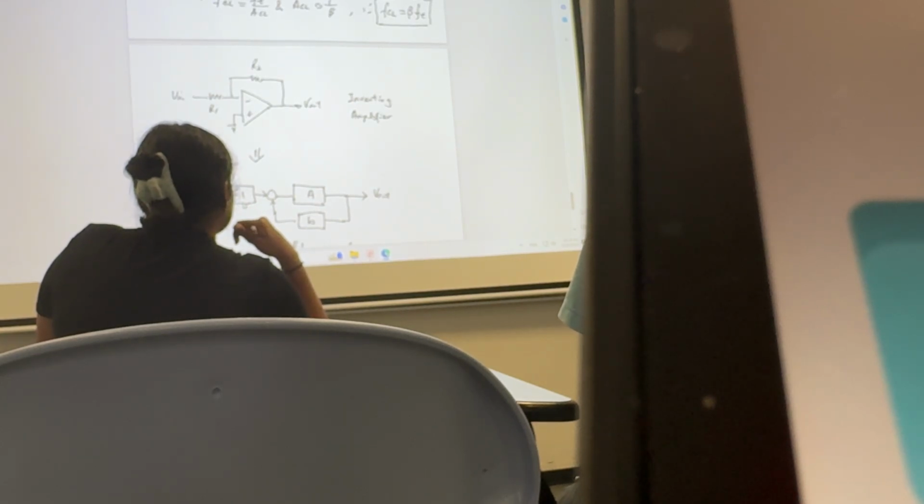Then you suppress V in, you go to V out, so V out times R1 over R1 plus R2. This is V epsilon 2. Epsilon 1 and epsilon 2, the excitation responses, on the virtual ground point, sum together, then you can get this equation 2, right?